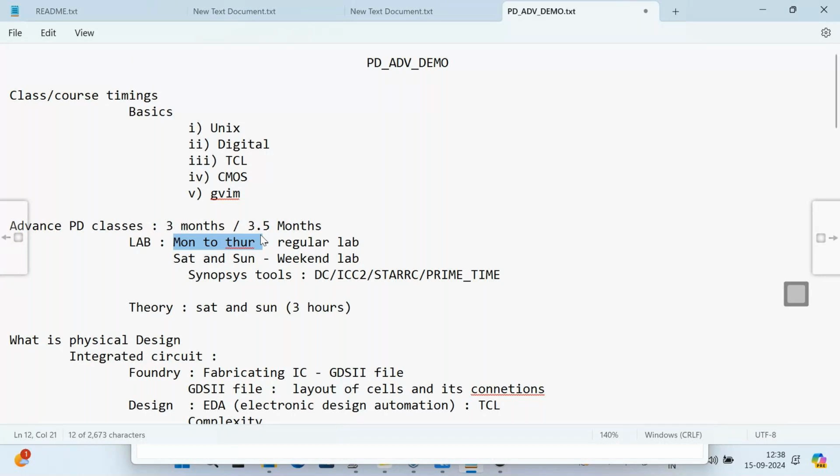Verilog code. We cannot write Verilog code for a PLL and op-amp and all. So they will design those things from the transistor level. That is called full custom design. And what we are doing here is the ASIC flow.